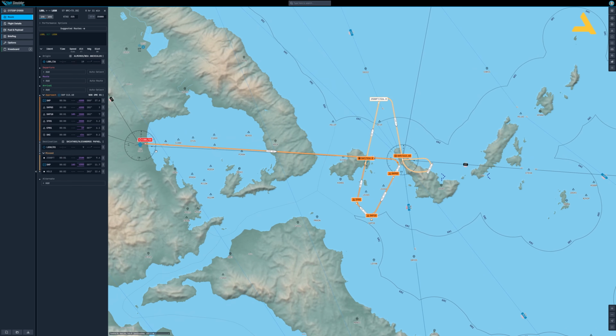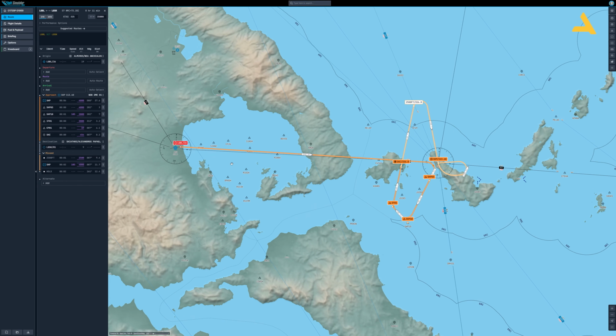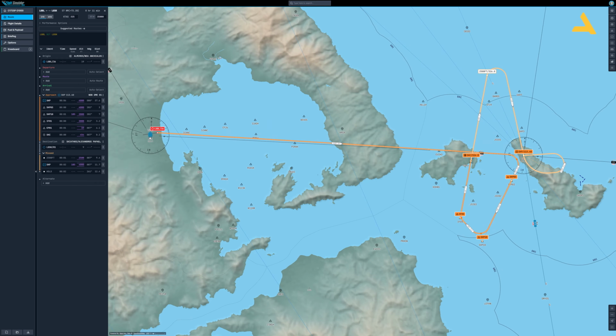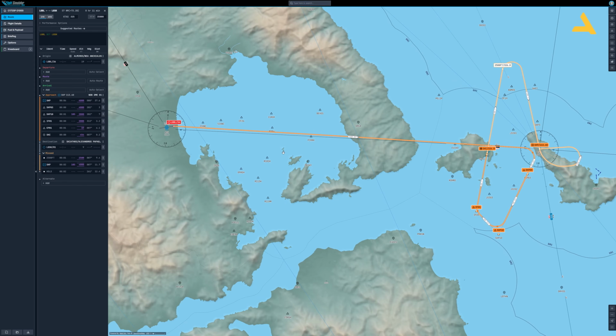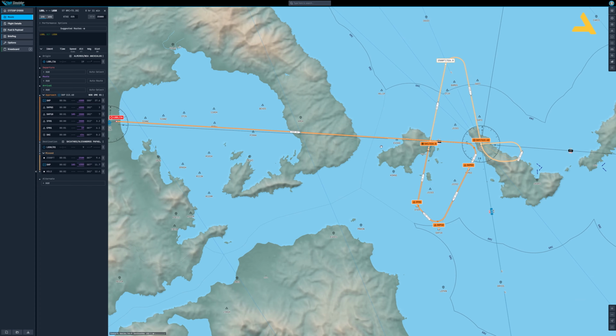To keep things simple, once I take off from this airport, I will keep on flying in this heading, 88 degrees. But I will be tracking both of the VORs. Why I'm doing this, I'll explain it to you. A VOR has a range of roughly 200 miles, so it can pick up the signals, but it's not really precise. As long as you are far from the VOR, you're not precise. You might be seeing that you're traveling in heading 88, but you might be deflected from the course. But as soon as you're near the VOR, your accuracy increases, and then you are exactly on this line.